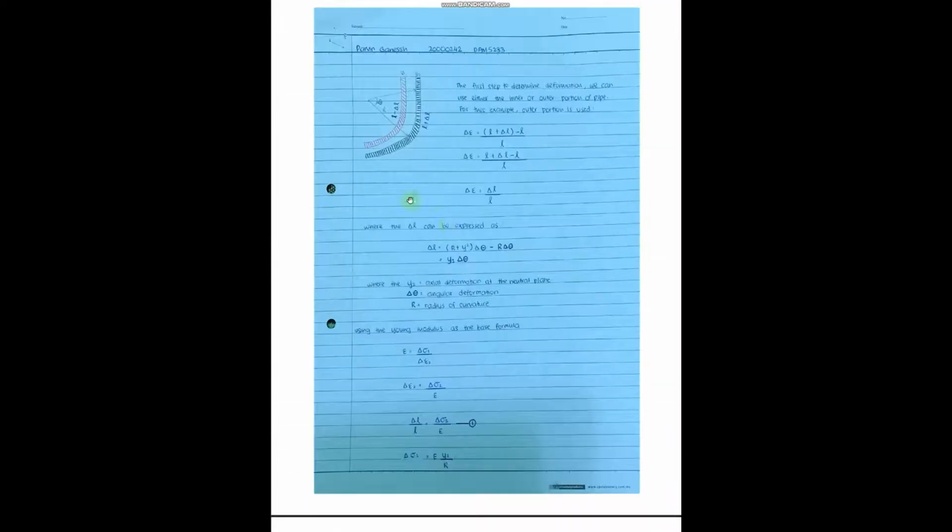But what we want is in terms of field units, so we convert all the parameters given here into field units, where y2 is expressed in inches, so we divide it by 12, and the radius of curvature is given in terms of radian over 100 feet, so we multiply it with pi over 180, giving us equation 3.